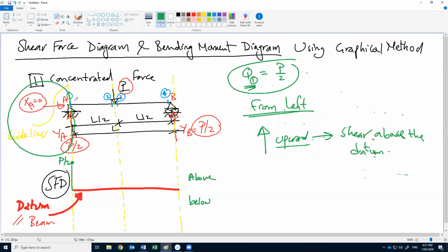Okay, from cut 1 to cut 2. In cut 2, this will be the part we deal with. So what will be the shear again? The shear again will be B divided by 2. To make it easy, we don't have to calculate each time from the beginning. From cut 1 to cut 2, do we have any forces applied?